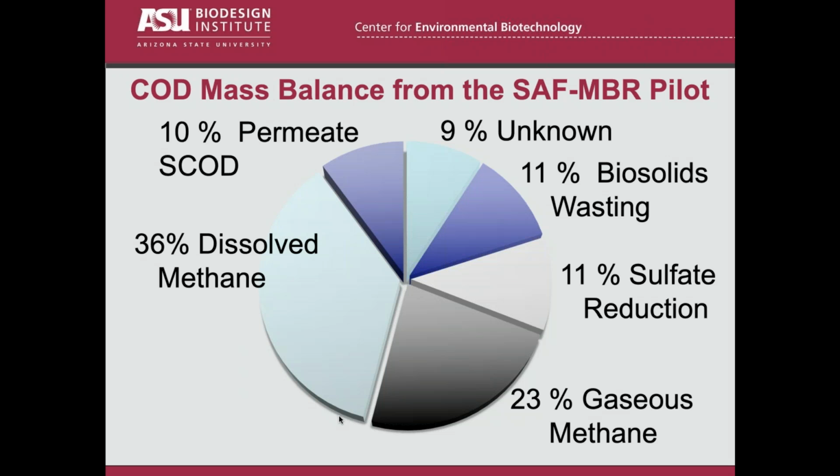That's in the bottom and lower left side. But you'll notice that in the SAF MBR study, there was more effluent dissolved methane than there was gas phase methane. Well, this is bad on both counts that I just told you about. So, we really can't do this.